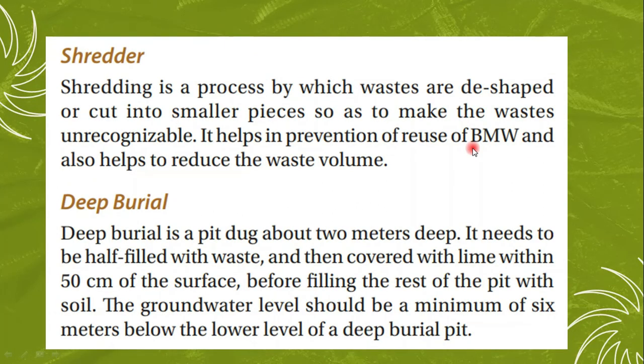Shredder. Shredding is a process by which waste is de-shaped or cut into small pieces so as to make the waste unrecognizable. It helps in prevention of reuse of biomedical waste and also helps to reduce the waste volume. Another method is deep burial. Deep burial is a pit dug about 2 meters deep.